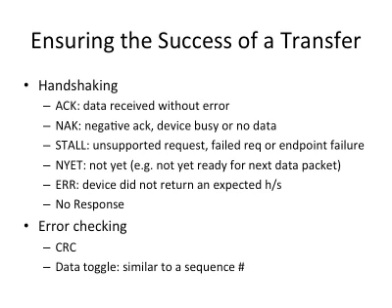To ensure the success of a transfer, you will need to do a lot of handshaking. Essentially, the endpoints of a pipe should do this handshaking to do acknowledgement. If the data transfer is successful, you will acknowledge to the other side. Otherwise, you give a negative acknowledgement to indicate the device is busy or there's no data.